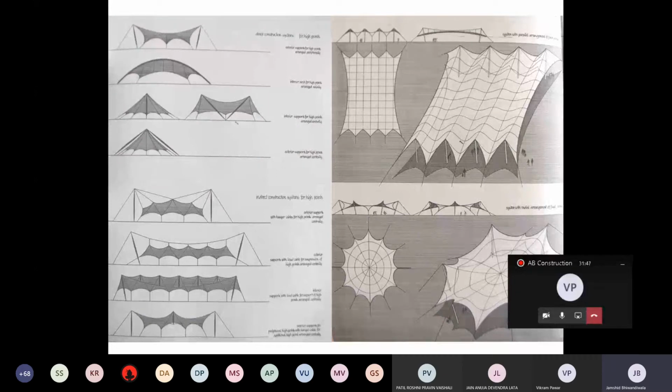The topmost diagrams are showing pivots in compression, vis-a-vis the diagrams to the left bottom, which are showing all pivots created through tension, suspension, all kinds of. So I think this diagram is very important to understand how I'm in a position to create peaks in a tensile structure by way of creating pivots, pivoted points or high points.